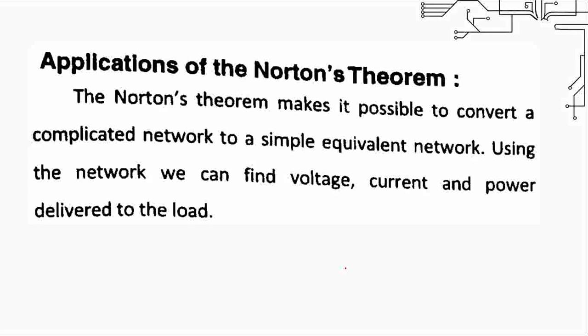Compare this theorem with Thevenin's theorem, and if a question arises in the examination that distinguish between Thevenin's theorem and Norton's theorem, your first point for distinguishing will be the statement of both the theorems. The second point will be, in Thevenin's theorem we are calculating open circuit voltage, in Norton's theorem we are calculating short circuit current.